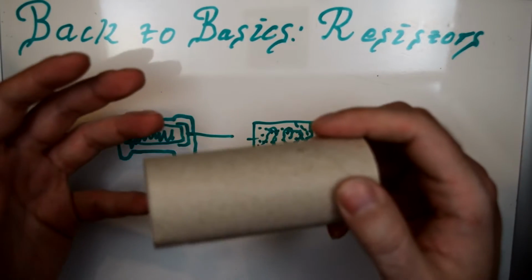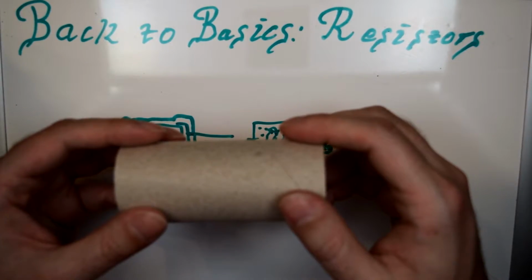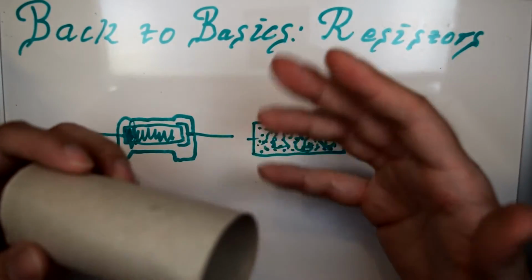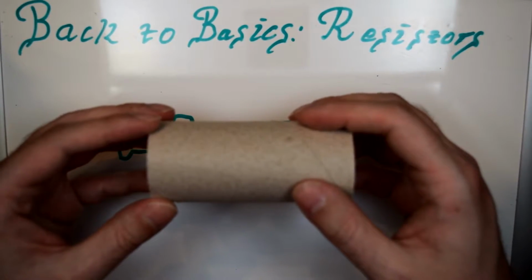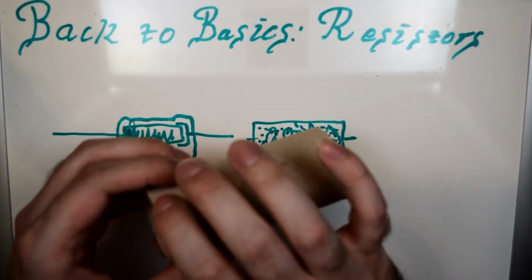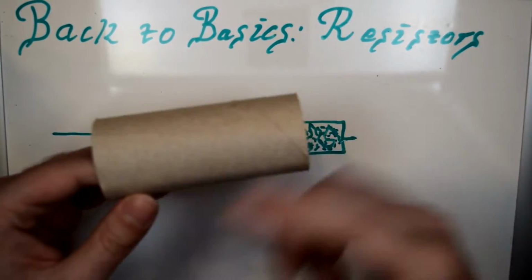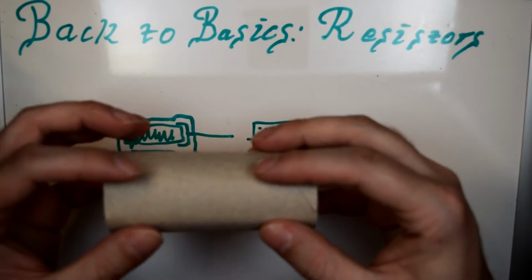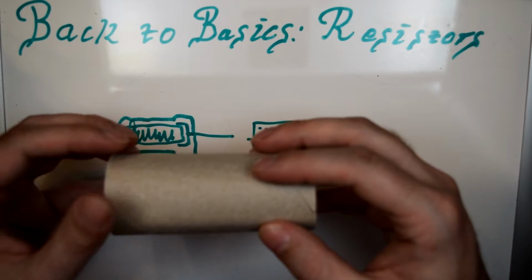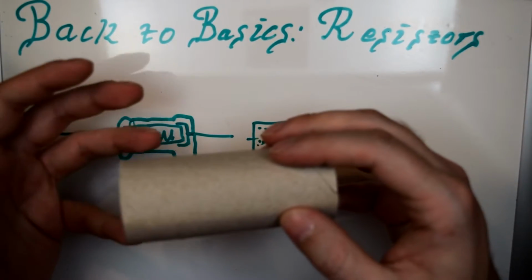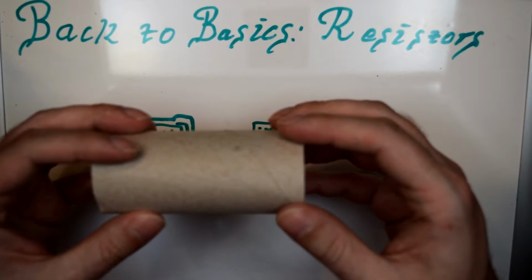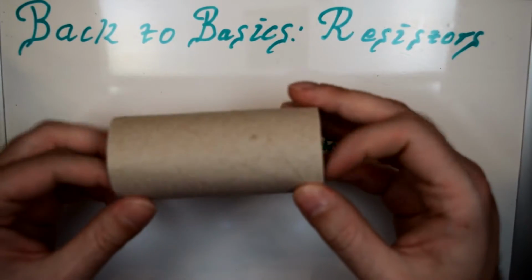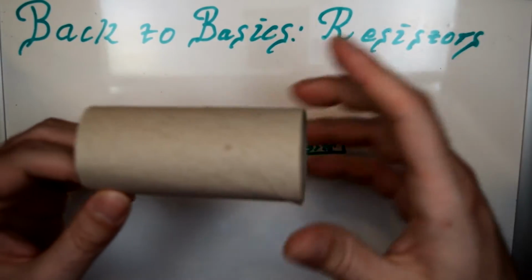They generally can prevent, well, not prevent, but they can lessen the inductive effect of the metal and carbon film resistors by making the ceramic material that the carbon and metal films are wrapped around have a very low permeability to magnetic fields, and that will help reduce the inductance of the spiral.